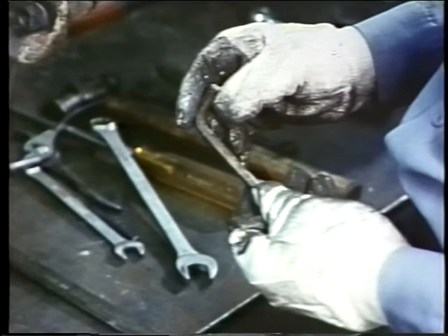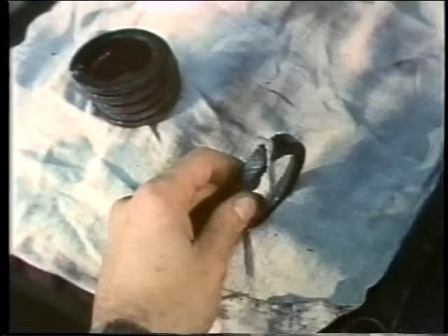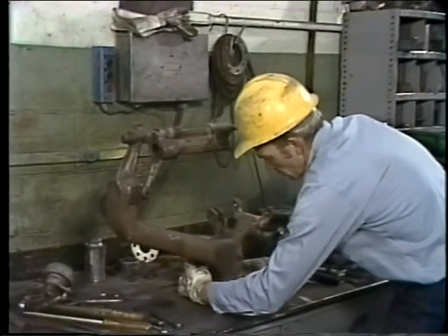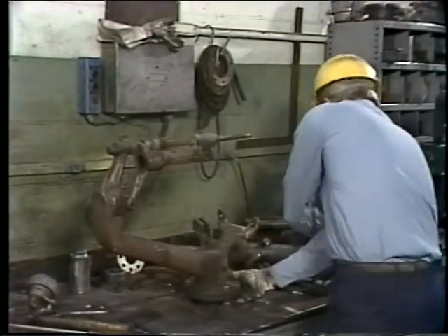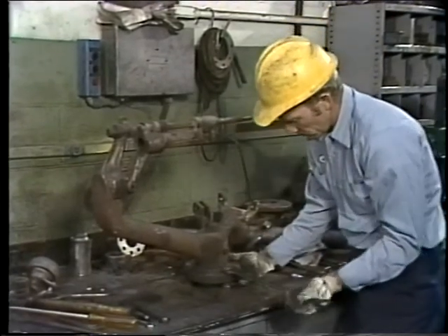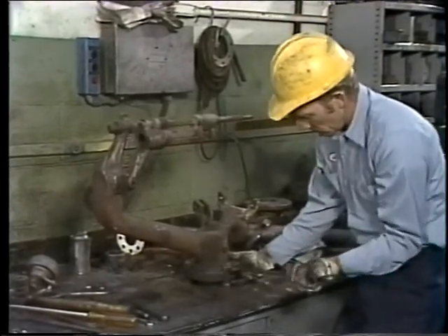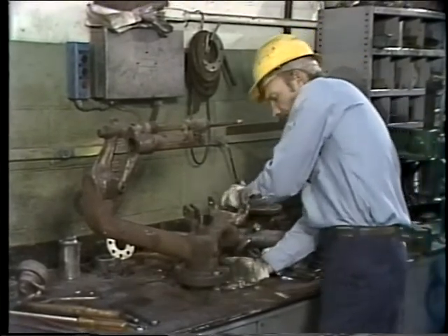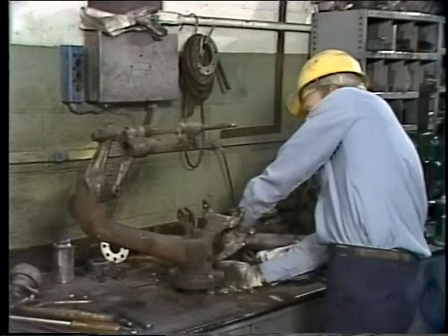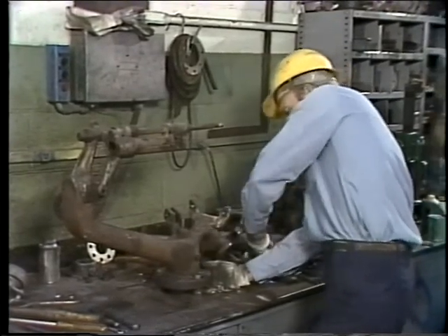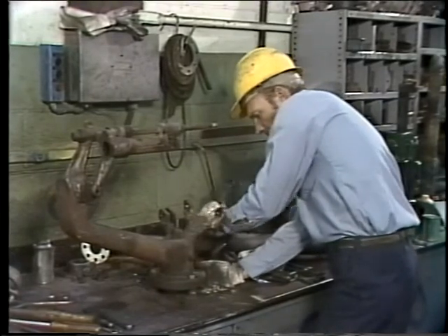After the parts and materials are laid out, and they've made sure everything necessary is there, our mechanic can start to reassemble the soot blower. Most of this is really a one-person job, just like what we've seen so far, but a helper is needed occasionally to assist. Basically, reassembly of the soot blower is just the reverse of the teardown. Since taking the valve apart was the last step of his disassembly, our worker is going to start by reassembling the valve using new packing.